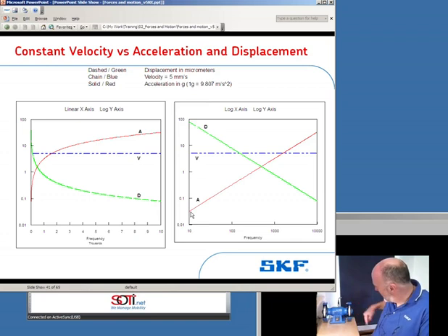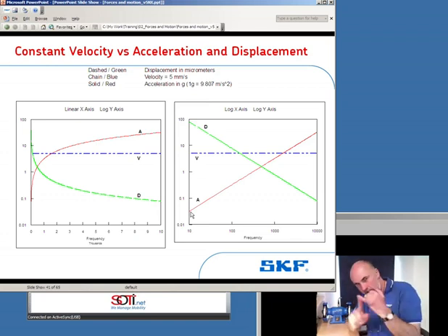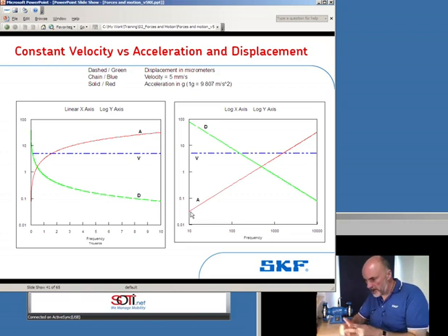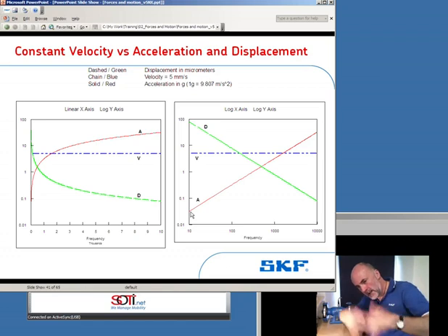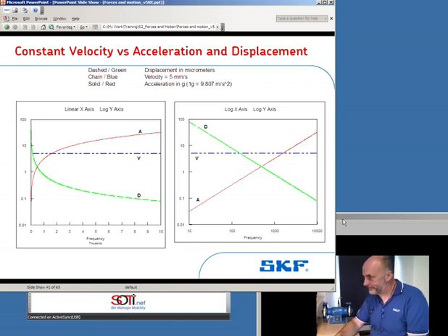I now speed this thing up to incredibly high speeds. Dentist's drill, 200,000 revs. Turbocharger inside your car, 200,000 revs. Gas turbines, there's a lot of gas turbines running at very high speeds. And gear mesh frequencies. Bull gears, for example, the gear mesh frequency, the rate at which teeth are meshing, can be hundreds of kilohertz.